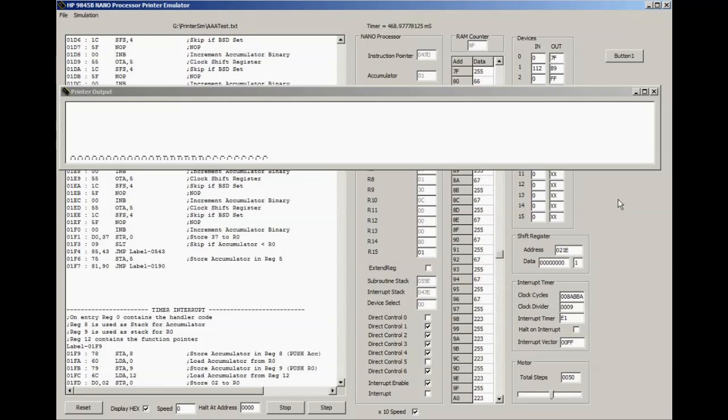And remember, we output A's, B's and C's. That's the next one. Notice turning to the next line of pixels. It's going through the RAM again to see what characters are in which position, and then it looks up the correct byte in each bitmap, forms a line, outputs that. The long delay between each one is to not only feed out the paper, but also to allow the burn time to print the actual character on the thermal paper. That's why it takes so long. Most of this is delay. So as you can see, just a couple of rows left to do.